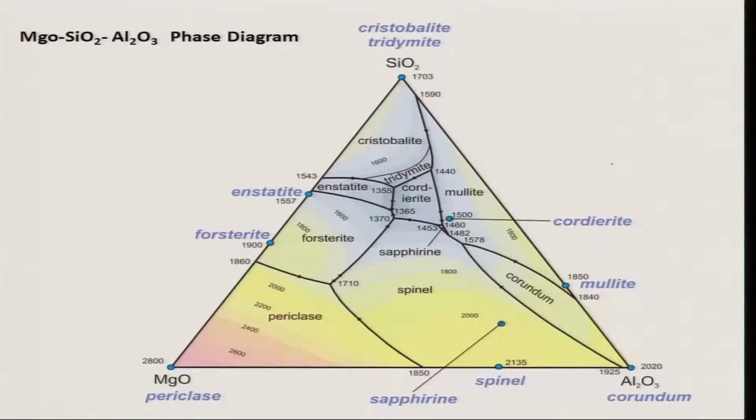The ternary phase diagram again consists of separate phases. Remember, let me first mark it. Periclase in the binary is what? MgO solution, correct. Spinel I told you. Let us first discuss the binary compounds. Between SiO2 and MgO you have forsterite. What is forsterite? Forgotten? Forsterite is Mg2SiO4, correct.